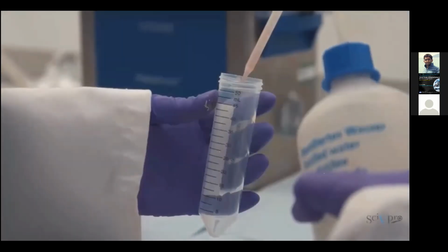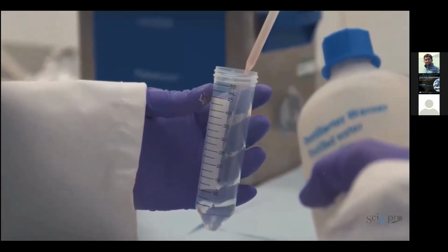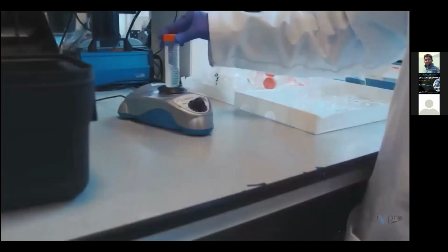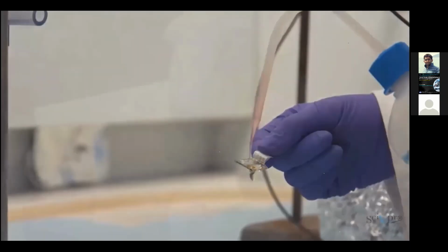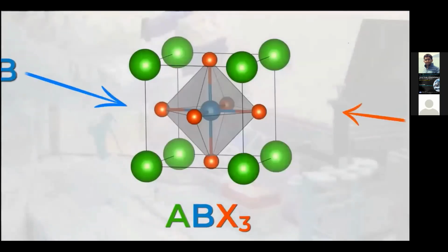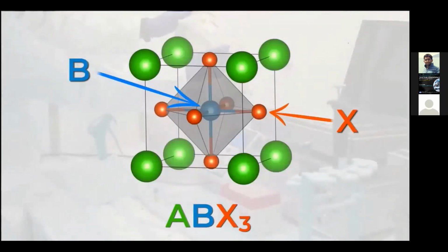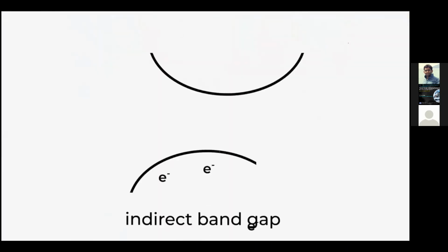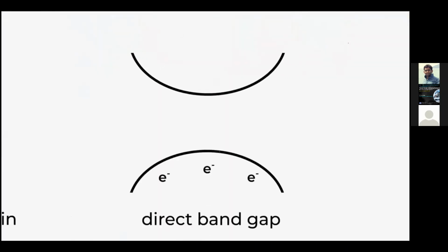Perovskites, like organic solar cells, are solution processable and also very defect tolerant, so they can be manufactured at very low temperatures very quickly and can also be printed on flexible materials. The two inorganic components of perovskites give it an edge over organic solar cells in development, as they allow the material to achieve very high efficiencies. Unlike silicon solar cells, perovskites have a direct bandgap behavior, which doesn't require a phonon, and other useful physical properties allowing solar absorber layers to be very thin.